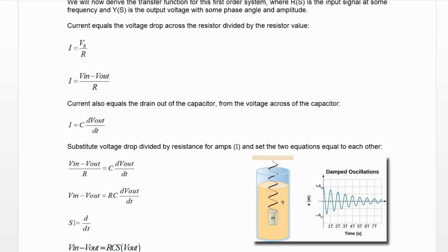As your manipulated variable comes out, it makes the splashing in the tank. And your process variable is measuring the output of the tank. And so in time, it's going up and down, up and down. And it looks like a sine wave. It's not flat DC out like most people think. It varies, and you get noise in it.